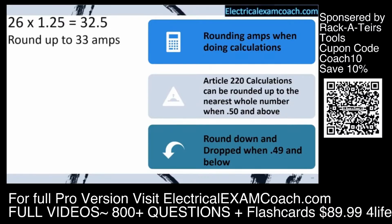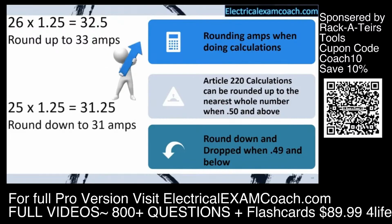with the wrong answer. So let's imagine we have this scenario of 26 amps, and after we do all of our math, it equals 32.5 amps. Well, in this case, we're going to round up to 33 amps. Now let's imagine we have a similar scenario, and when we get our answer, it's 31.25. Well, in this case, it's 0.49 or less, so we are going to round down in this scenario. And that's how we're going to deal with all of our numbers in load calculations.